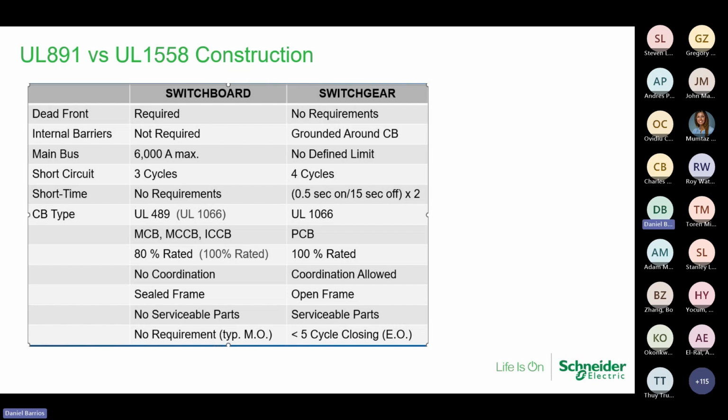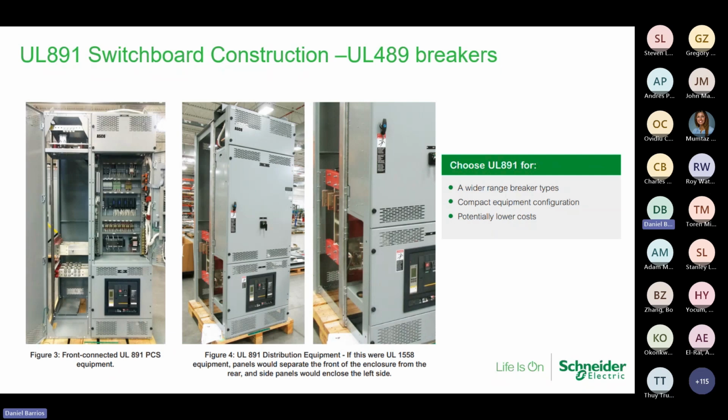Another comment is that if you are doing the onboard paralleling, they're doing all of the biasing to their governor and to their voltage regulator. Whereas if you come to our final comment here, when you're going to the redundant and resilient, we are controlling that. We need to know what system you have, and we are actively controlling the synchronization of those systems. If you haven't ever walked up to one or had the opportunity, again, please come to our witness test if you have a project that you're available for.